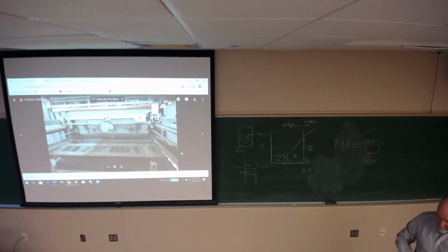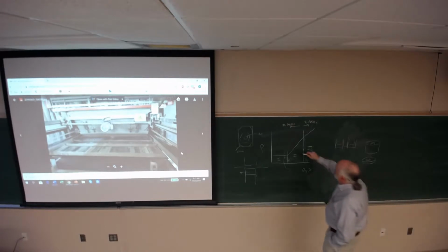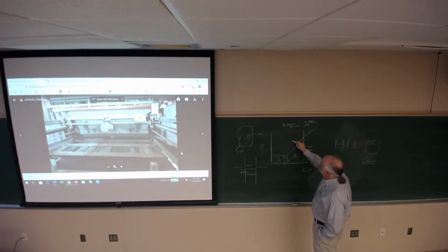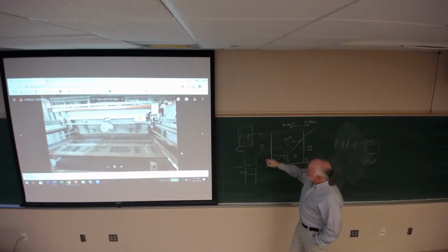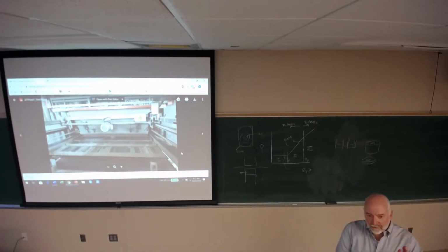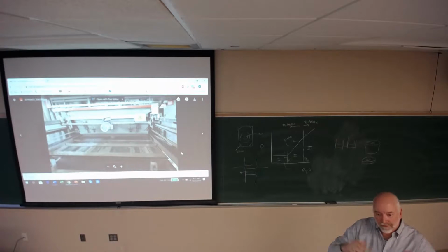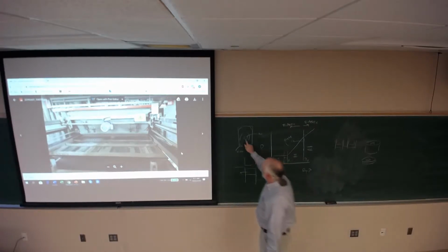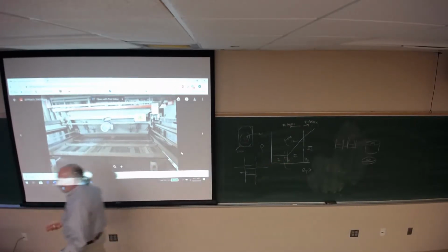Okay, so if you press on a material, if you shear it, the density goes up significantly, measurably different, and P2 decreases also, by the way. P2 decreases a lot, okay? So this is a shear compaction, right? And that explains these corners. Because in the die, the material is being sheared at that corner, and so the density goes up. And there's no shear in the middle, so there's no density improvement in the middle.